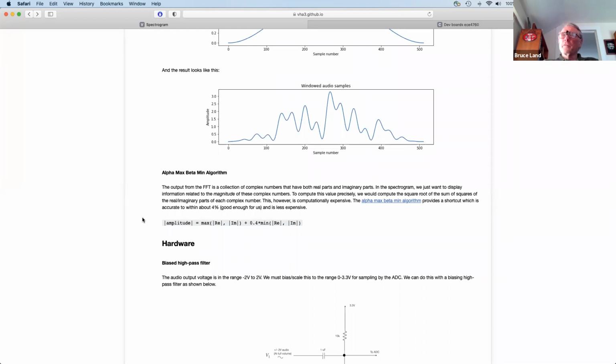The answer is 50% overlap in the samples. So you oversample so that you can always get full data. We're not asking you to do that because what Hunter hasn't said is that there's an assumption that the signal is stationary over the window.